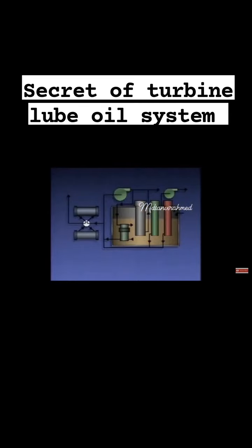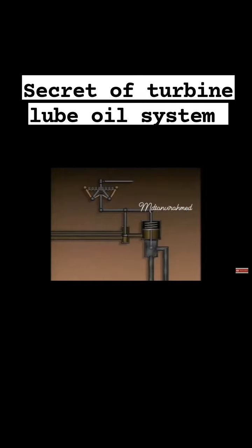Operating efficiently. An important aspect of turbine operation is lubrication of the turbine shaft bearings. This is accomplished by the turbine lubricating oil system. Oil is also used to operate valves that are designed to control turbine speed. Turbine speed control is another important aspect of turbine operation.